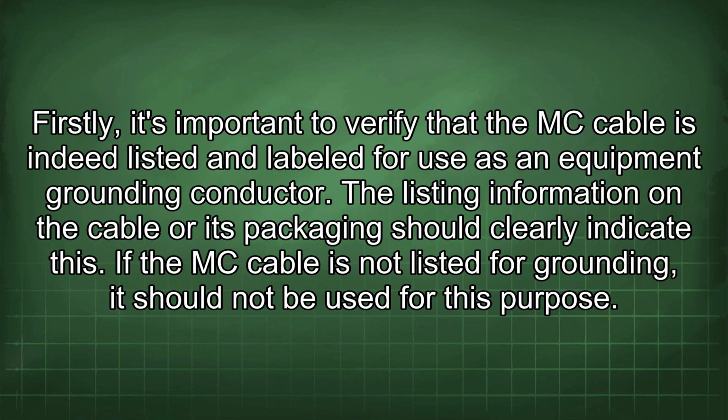Firstly, it's important to verify that the MC cable is indeed listed and labeled for use as an equipment grounding conductor. The listing information on the cable or its packaging should clearly indicate this. If the MC cable is not listed for grounding, it should not be used for this purpose.